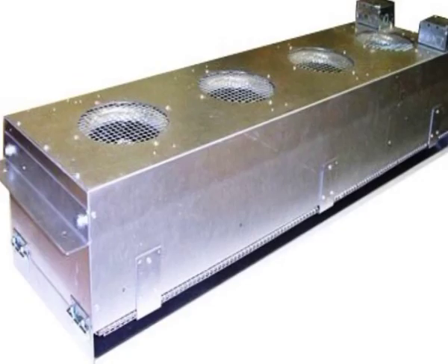In case of infrared drying, heat releases at a predetermined location inside the food material on incidence of IR rays, and thereby heat and mass transfer will be in the same direction, that is from inside to outside. So, less resistance is offered for the mass transfer.